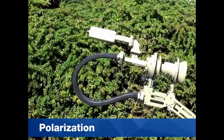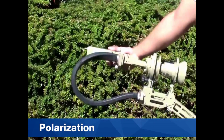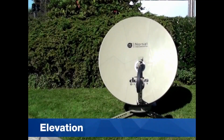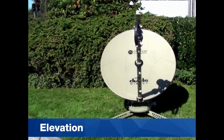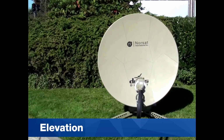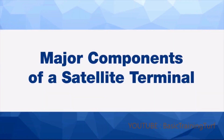Satellite terminals will receive and or transmit on horizontal, vertical, or circular polarization. Typically, rotation of the feed assembly will adjust the polarization to match the satellite's polarity. Elevation refers to the angle between the beam pointing direction and the local horizontal plane. For adjustment, the satellite terminal has an elevation rod, which allows you to move the reflector up and down on the vertical plane. Now that you have a little background on satellite terminals, we can now talk about the major components of the satellite terminal.